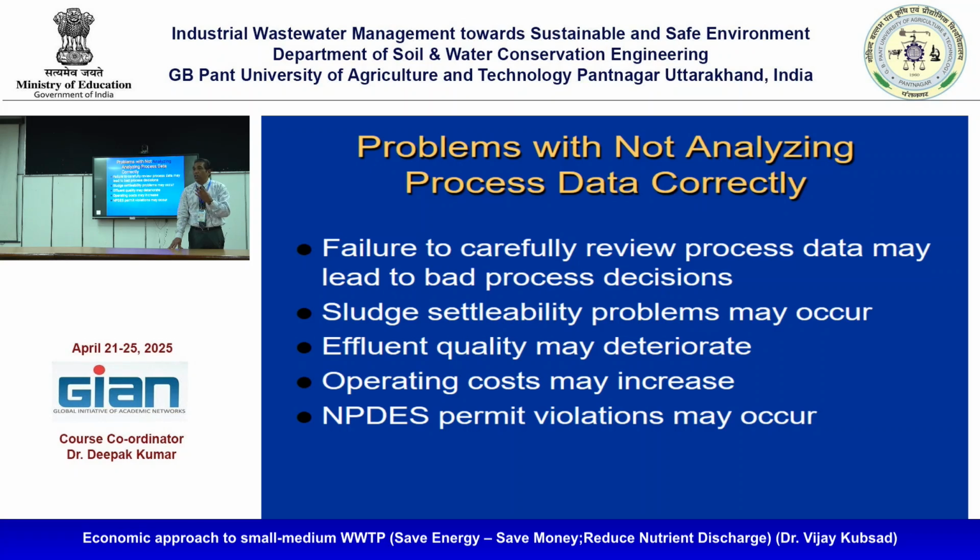Seasonal variation. We take the variation at the time of the organic loading, the variation with different hydraulic loading, all the combinations you will do. Right? Yearly variation, hourly variation, you will study all that. Then you will see a consistent trend. That is why when people submit the report, I ask, did you do the trend analysis?